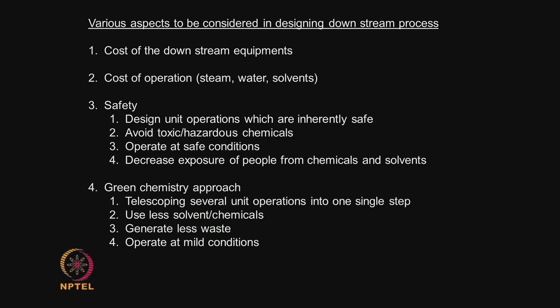Cost of operation. Does it require water? Does it require solvent? Does it require steam? Does it require hot oil? Because each one of them will have its own cost. Can I do things with the steam or hot water rather than going into hot oil, which may be expensive? Can I recycle this hot water? Can I recycle this hot solvent? And so on. You need to consider the cost of operation.